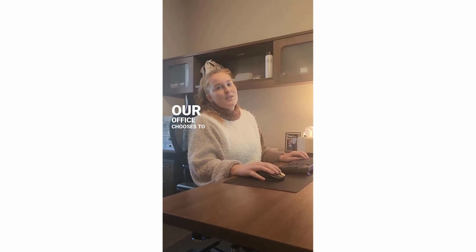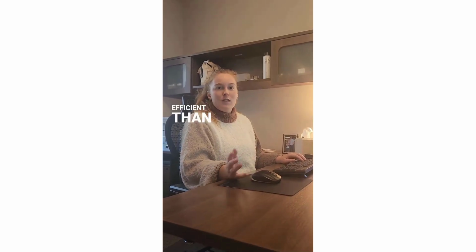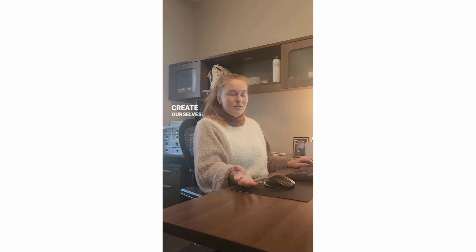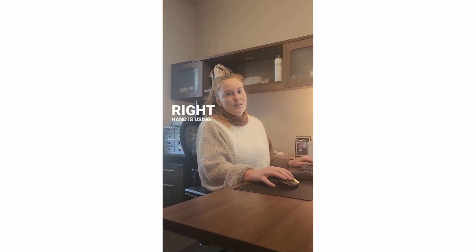Our office chooses to use hotkeys for almost everything because we feel it's quicker and more efficient than using your mouse to find the tool on the toolbar. We use the ones that Chief Architect already has and then ones that we create ourselves. We recommend using the keys on the left side of the keyboard so that your hand can already be resting here while your right hand is using the mouse.